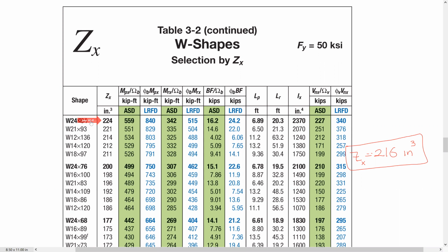And here is for the shear, and we will see how to do that later. But here, guys, W or wide flange 24 is the depth, okay? 84 is the weight. So this is the self weight of the beam, 84 pound per foot, once I select the beam. So let's get back to our example and see how we're going to continue with this one here.